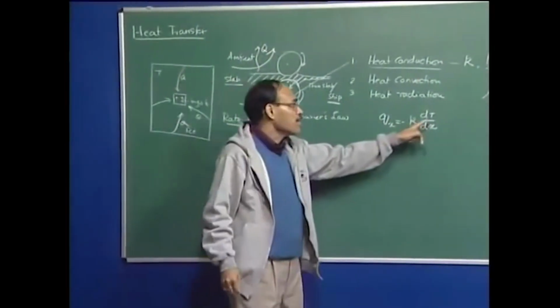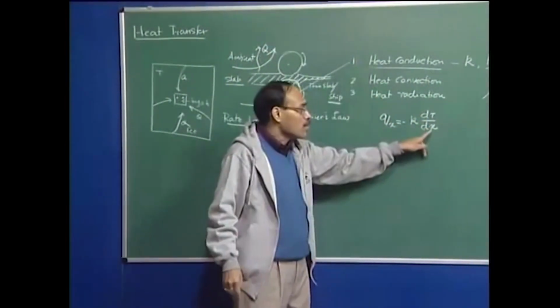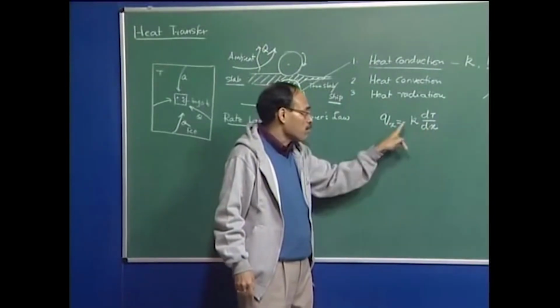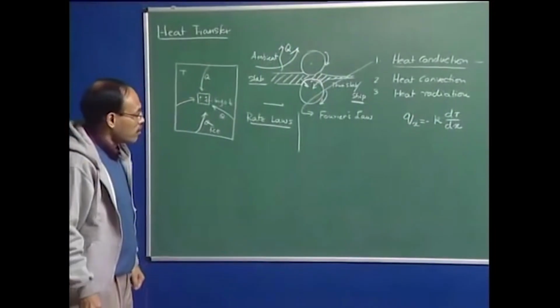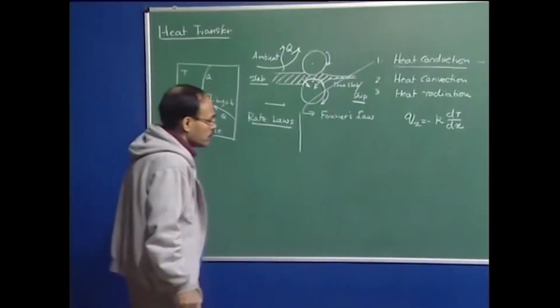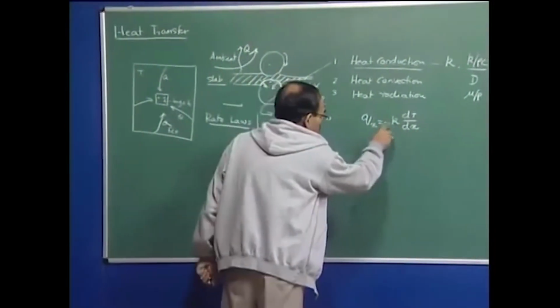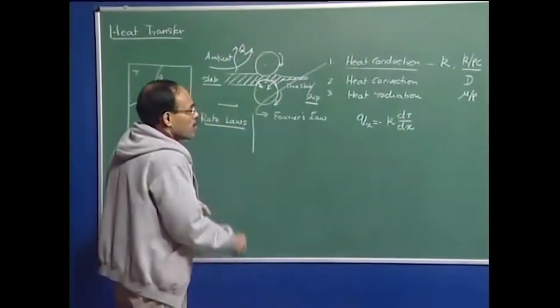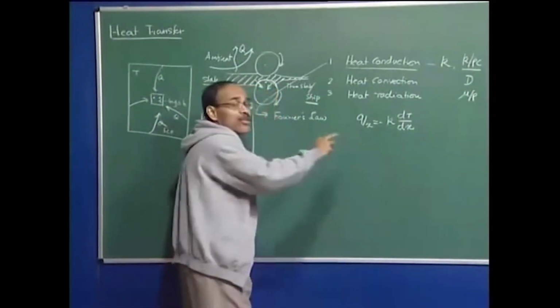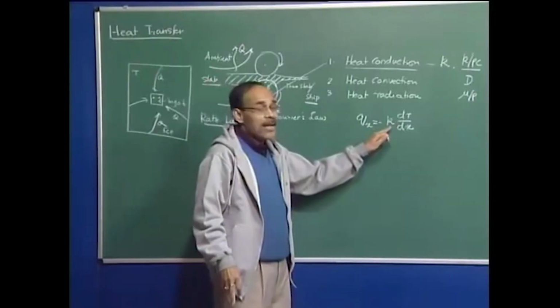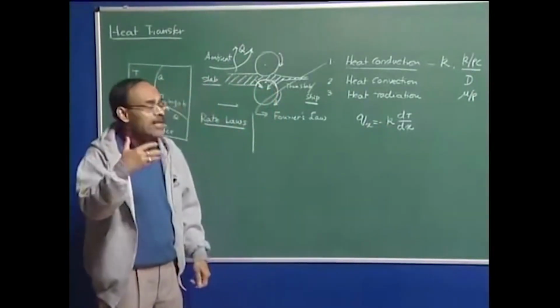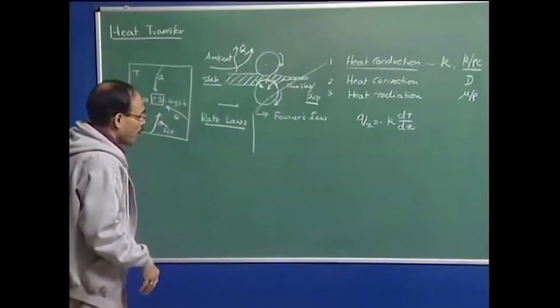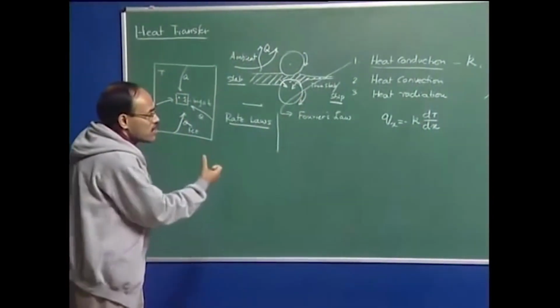Heat flows from a region of higher temperature to a region of lower temperature, and that is why it is preceded by convention with a negative sign. Now this thermal conductivity: for example, I can have a Qy, I can have a Qz, and in that case I may not have the same K in all three directions. K may be a direction sensitive property, or structure sensitive property.